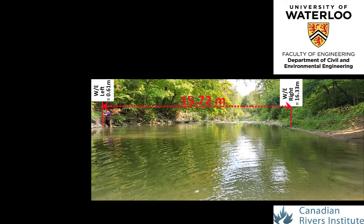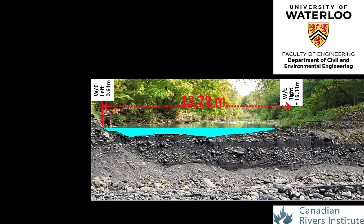Also, from the first wading across the cross-section, it was noted that the channel was relatively uniform with no significant spatial variations in water surface velocities nor bathymetries, suggesting that the channel could be discretized evenly without the need for additional panels to be added in more concentrated flow or topographic locations.